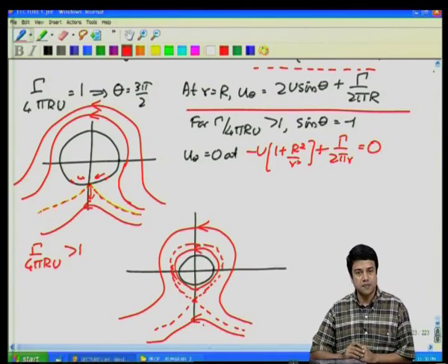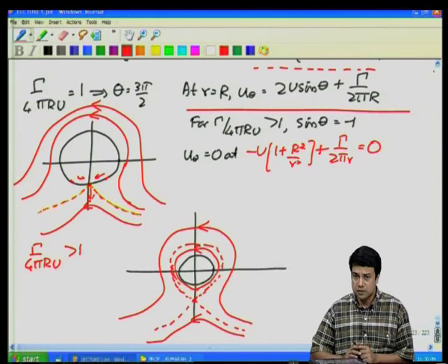Okay. So, this basically represents the flow around a cylinder. One might be tempted to think that this kind of flow can be achieved if we had a rotating cylinder. That is not quite true, because in potential flow we have a zero normal velocity boundary condition, but the tangential velocity in general is non-zero. So, just by rotating the cylinder we cannot generate a flow in the fluid, because we are not satisfying the tangential velocity boundary condition. We will come back a little later and see how one can achieve these kinds of flows.